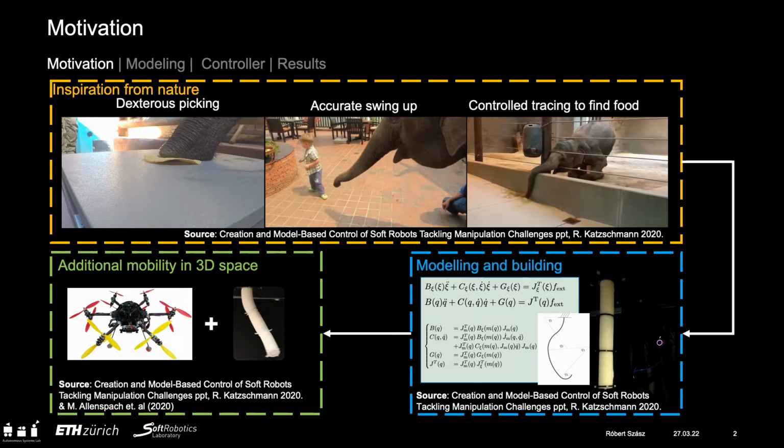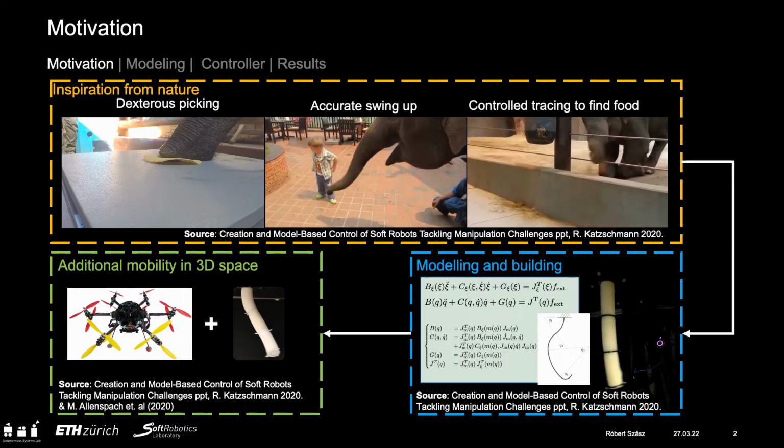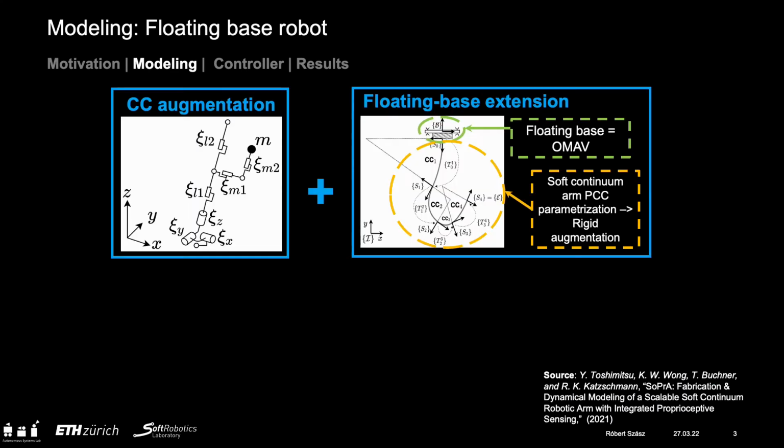with any orientation. The main obstacle in current endeavors on soft flying manipulators is the overly complicated model of the soft parts. To tackle this problem, and to enable real-time analytical control, we modeled the soft robotic arm with the Piecewise Constant Curvature, or PCC, and Augmented Rigid Body Model, in short ARBM, hypotheses.